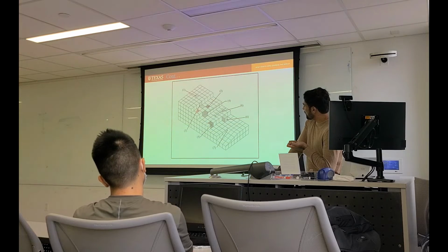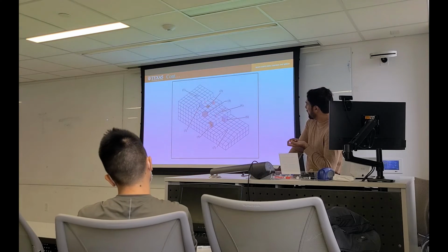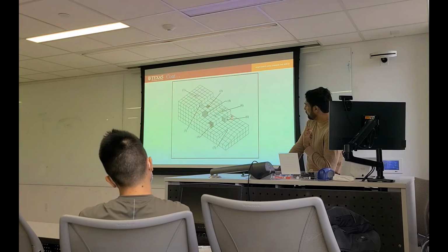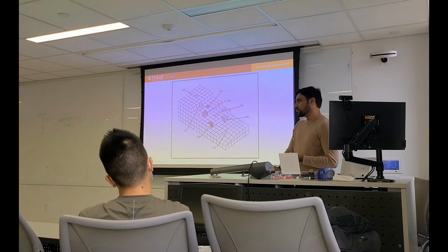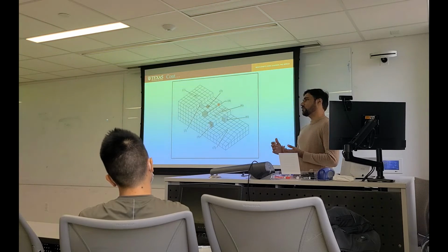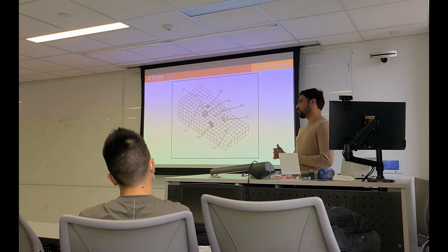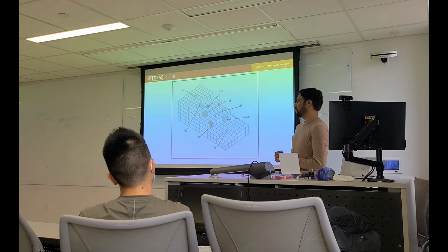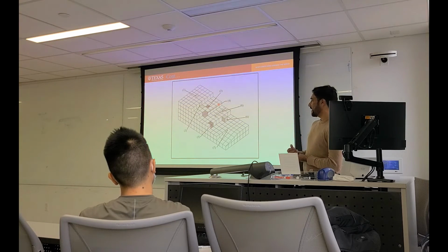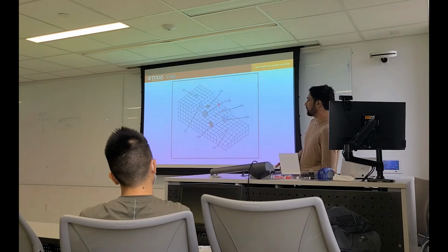So these are the kinks, terraces, several kinds of defects. So they are actually starting the nucleation. That's why to get step flow growth, meaning without 2D islands, a very uniform thin film that has very uniform morphology, it is grown because of the step flow growth.